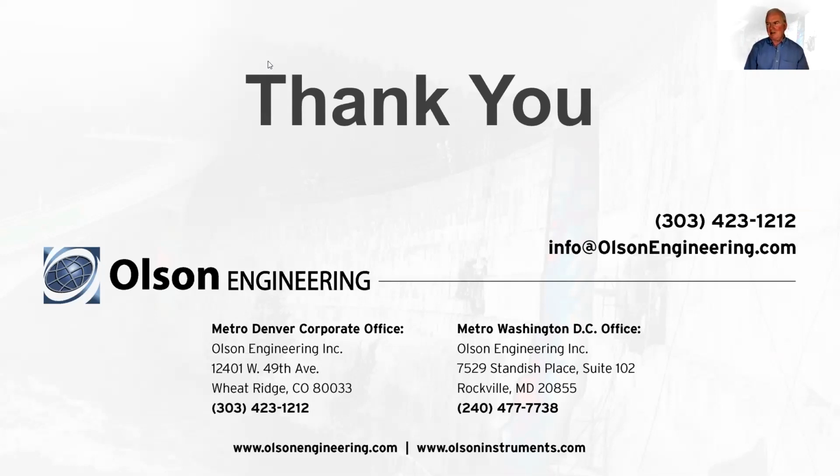But a gentleman named Dr. Nils Ryden from Sweden addressed this specifically for the difficult problem of going on a concrete pavement and determining the surface wave, shear wave velocity, and shear modulus of the underlying road base and subgrade. And he did that by modeling specifically the higher modes. So it can be done. It hasn't become so commercialized yet. We're working on it. Some other folks are looking at it. So you can deal with it. But it's a good question.